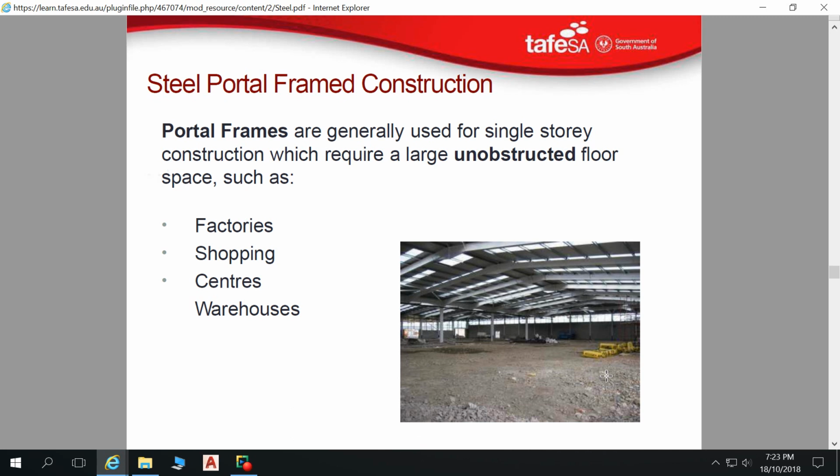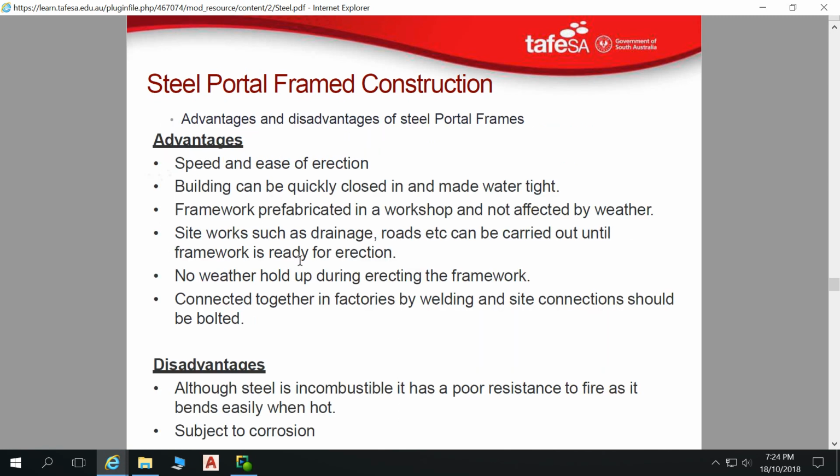And that's why I see these portal frame constructions predominantly for all these hay sheds and machinery sheds, is you don't want to have that interruption of columns everywhere. So farmers are putting these up because they can stack the whole thing full of hay without having to work around columns and things like that. They can drive their semi-trailer in here and they can turn their semi-trailer around inside the shed. That's a fantastic thing. So factories, shopping centres, warehouses, etc.